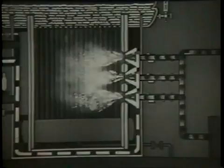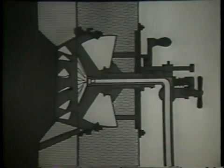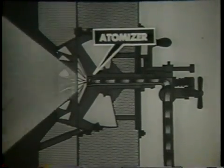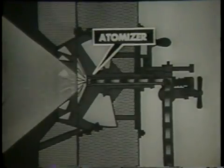As we have seen, the burners in a boiler provide the combustible mixture of air and fuel oil that is burned in the boiler furnace. As seen in this view of a typical burner mounted in a furnace wall, the burner's atomizer reduces the fuel oil to finely divided mist-like particles. That is, atomizes the fuel oil.